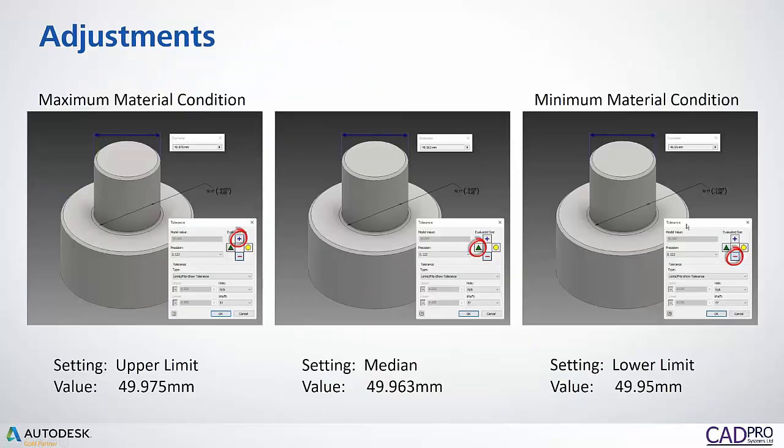So that gives you a few options as to where you shoot. If you're machining and it's coming out undersized, you can go and shoot for the top limit. You're probably going to then end up in your range. If you machine the part and it comes out oversized, for your second off, you can hit the minimum limit. But most times, if we aim for the median, hopefully we'll be somewhere in the right range. Whereas obviously, if this was just a nominal size and the limits mean that I have to be over, we'll never actually get there without applying some kind of compensation downstream.